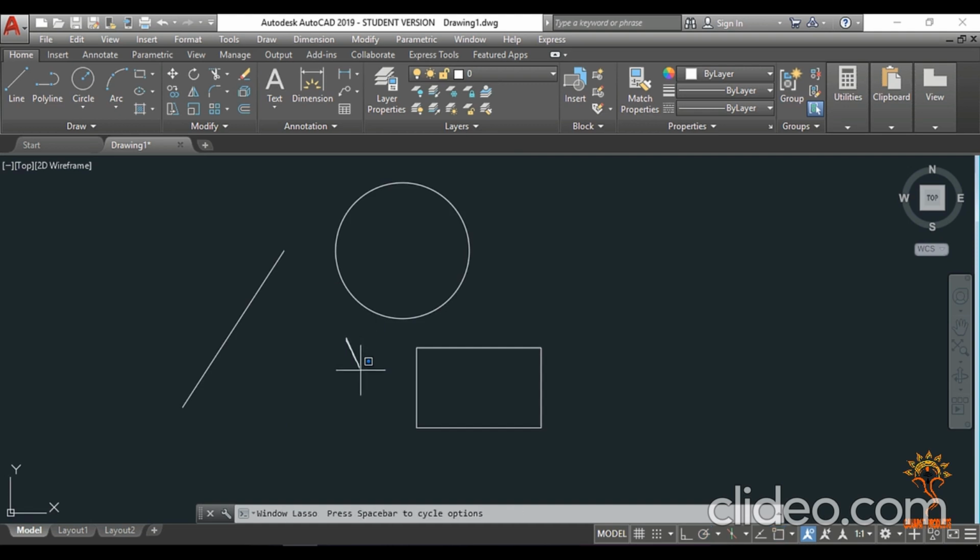Now we come back to the training of the AutoCAD functions. First, we move our mouse to the workspace settings and choose the drafting and annotation button. If we needed to do a 3D model, we would choose the 3D basics or 3D modeling buttons.